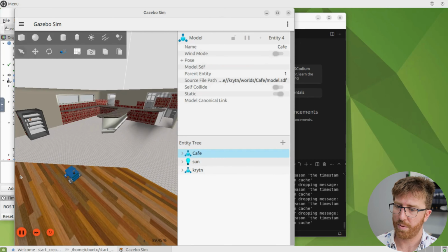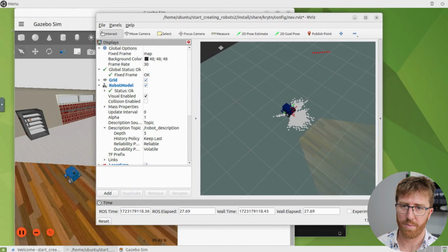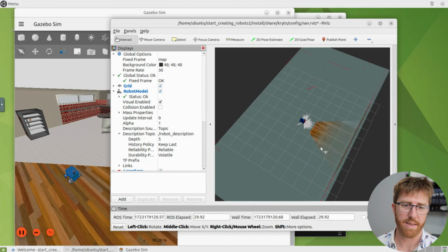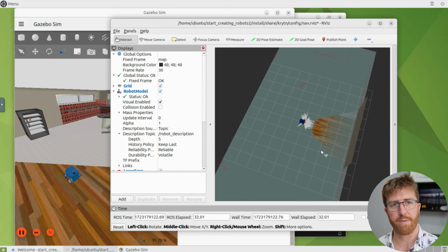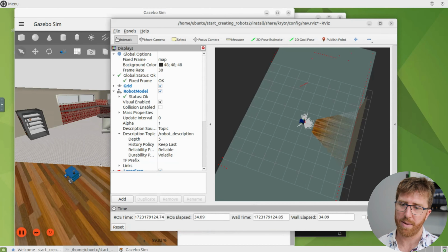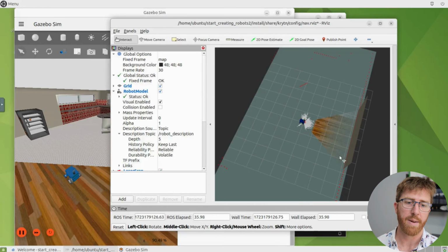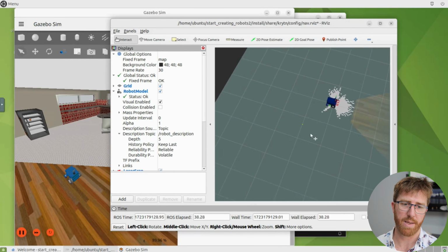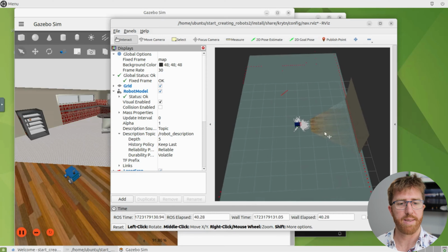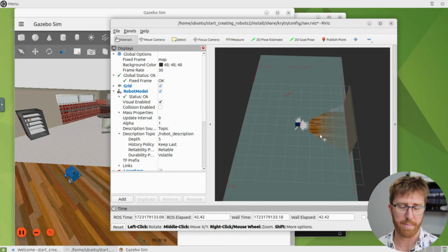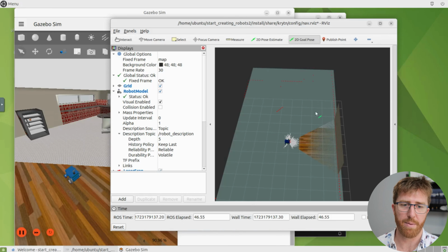And we've also got this other thing which we've started, which is called RViz. This is a system for visualizing the robot data from the perspective of the robot. So you can imagine this Gazebo sim is like the world, and this is like the robot's perception of the world. And we've already set up a simultaneous localization and mapping and a navigation system.